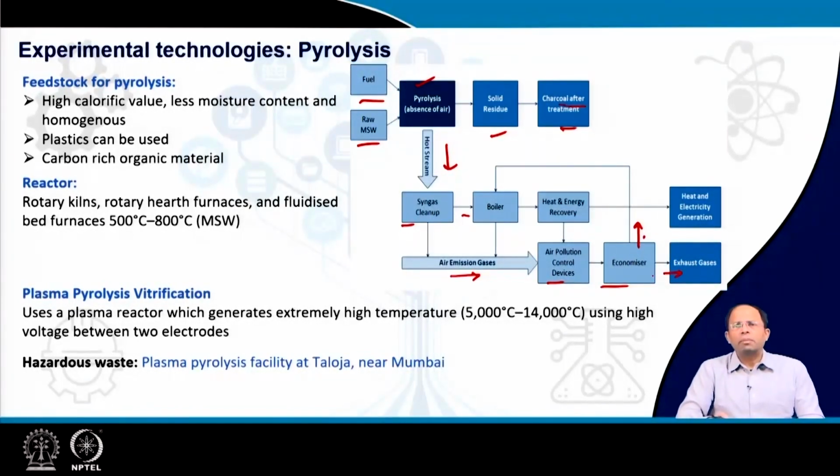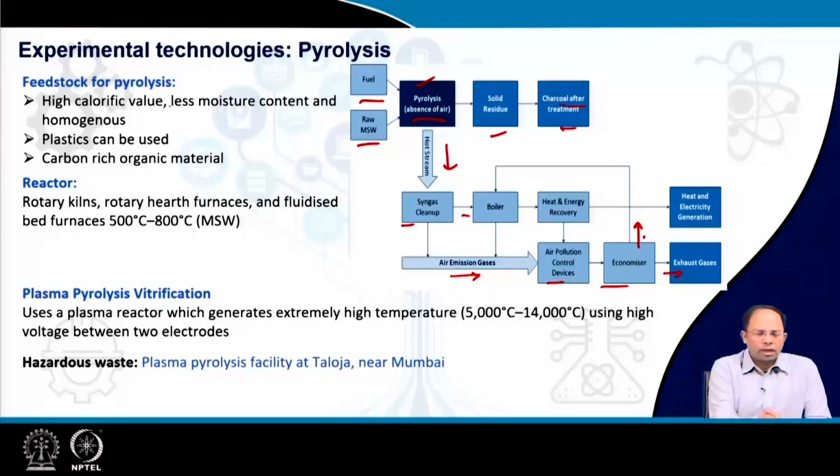So this is more or less the same as the incineration process. The only thing is it happens in the absence of air. So the feedstock for pyrolysis is high calorific value waste. And of course, as you understand, the quality of waste should be even higher in terms of calorific value compared to standard incineration. Less moisture content, and the waste should be homogeneous. Plastics can be used. Over here, we will suggest the use of plastics.